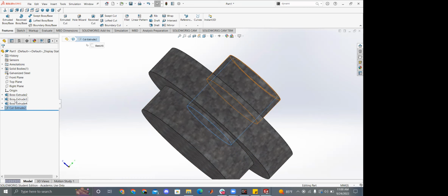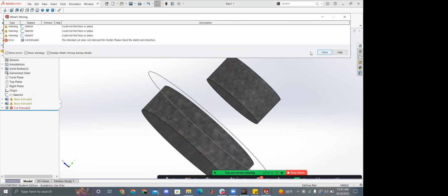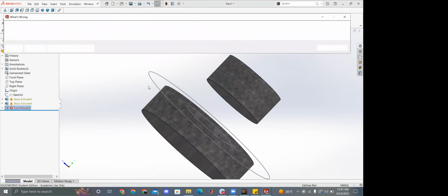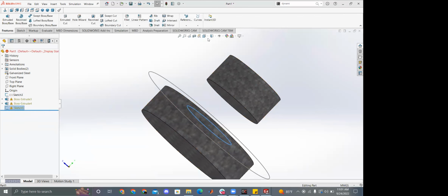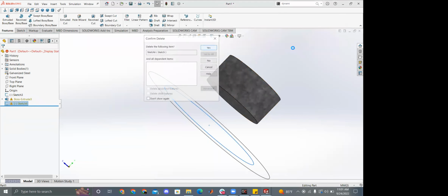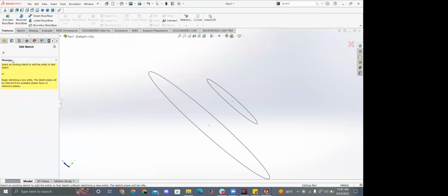If you're going to make parts that are essentially a bunch of bases stacked up, please don't use a bunch of extrusions. Just do a revolve. Otherwise it's going to take you a bunch of features. So yeah, it's really cool. See, there's a lovely sound: what happens when you delete things that are dependent?